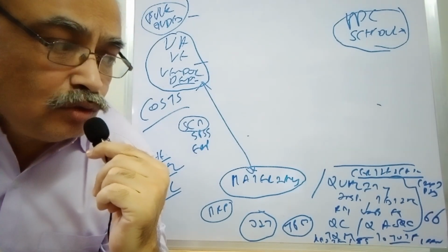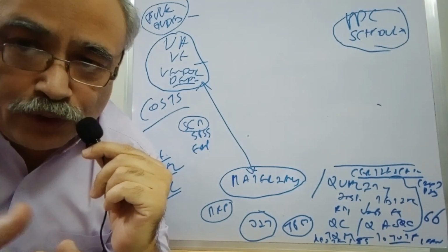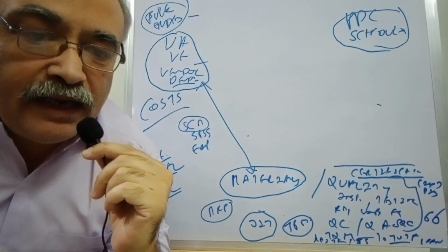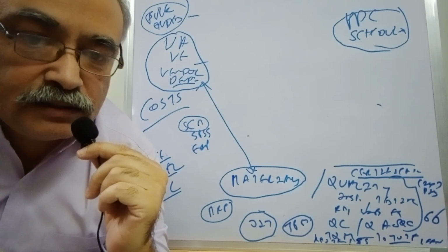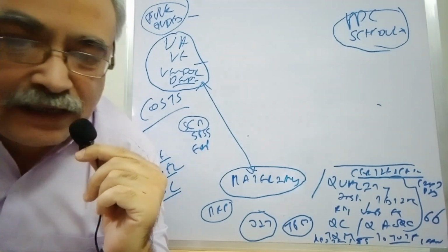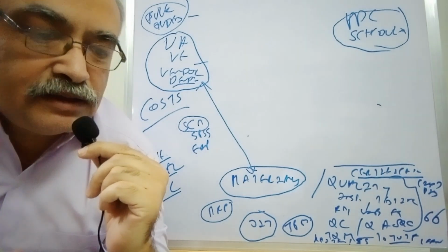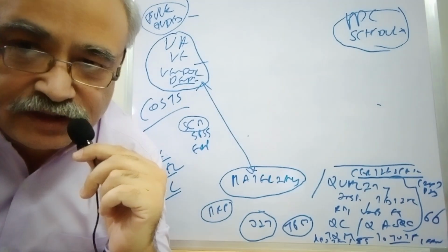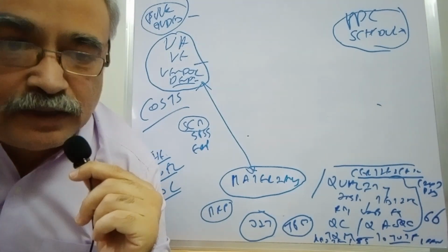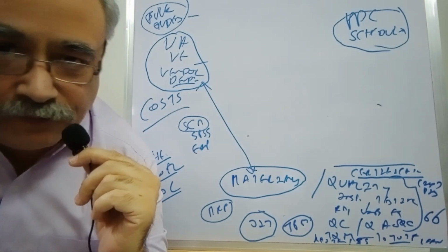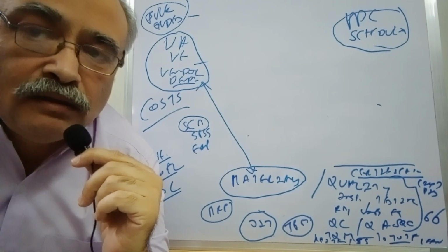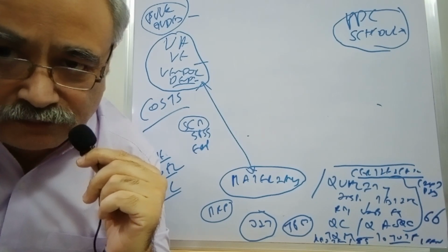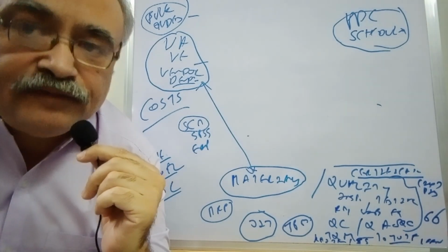Toyota even took the concept of lean manufacturing, how to produce quickly, single minute die exchange, SMED, where you can quickly turn around things, you can quickly schedule things. There is zero wastage, zero time wasted, material handling is reduced, inventory is reduced, costs are reduced. So that is the lean concept, where the production becomes very efficient. That is a lean concept which has been pioneered by Japanese companies, especially Toyota. So it has revolutionized manufacturing in certain areas, in materials, the inventory part, as well as the quality part, the efficiency and the cost part.